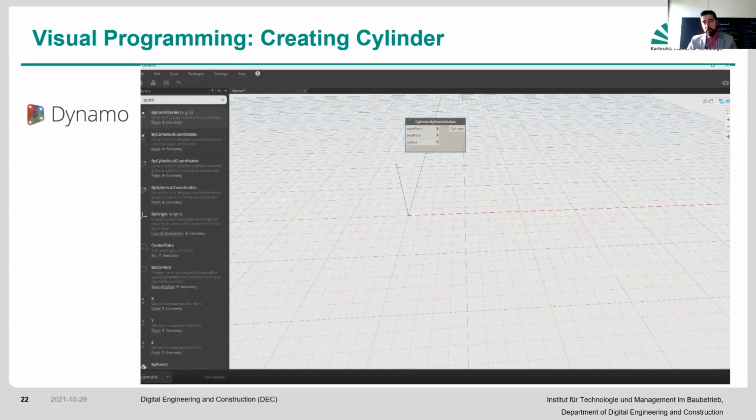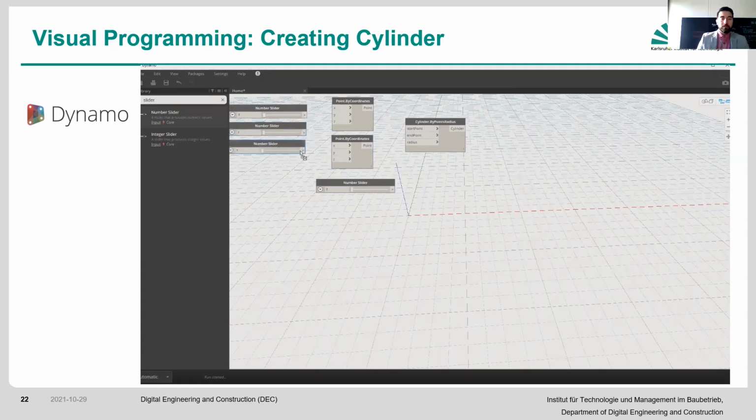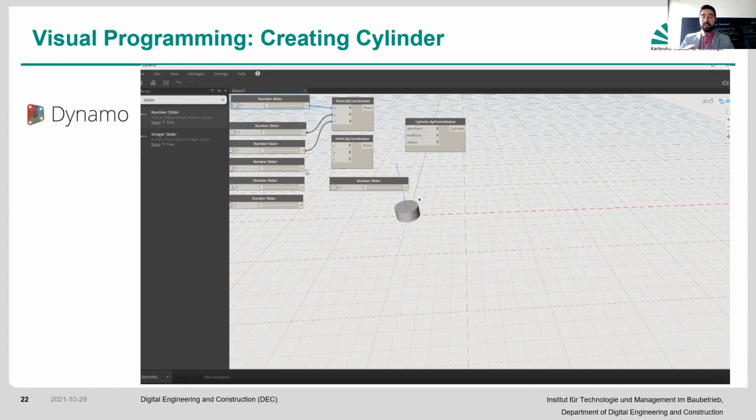Again, with this function particularly, there are other ways of defining cylinders as well, right? But this function likes to do it by means of the start and the end, which represent the axis of your cylinder, and then the radius. For each and every one of these, you can define a slider number. These would be 7 different inputs, provided by 7 different slider numbers. And as you're changing those slider numbers, everything related to your cylinder would also change accordingly.